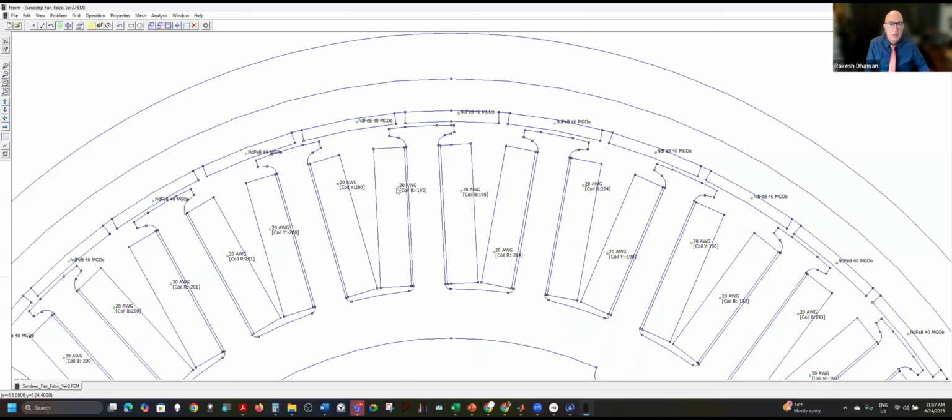So then this is your coil, and this is coil B. So you have a coil R, coil Y, coil B. I'm going to select this coil here, and it has 195 turns, and I have to set the direction of the turns, 20 gauge wire, and coil B is part of group 2. And then we go and see this coil here, and this one is 200 turns.